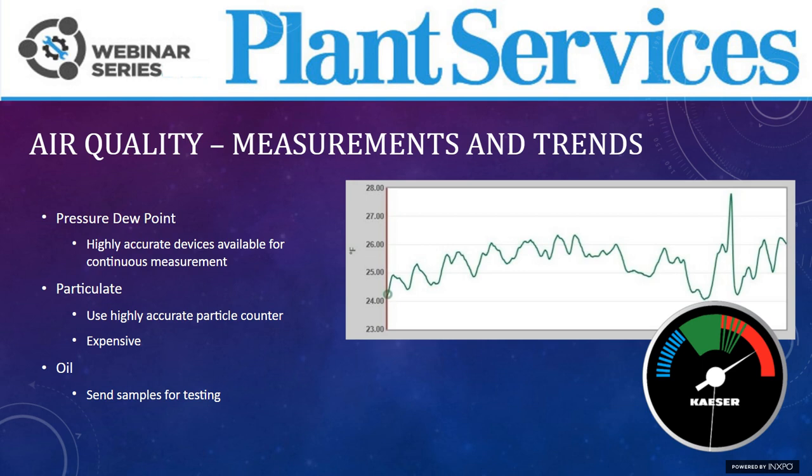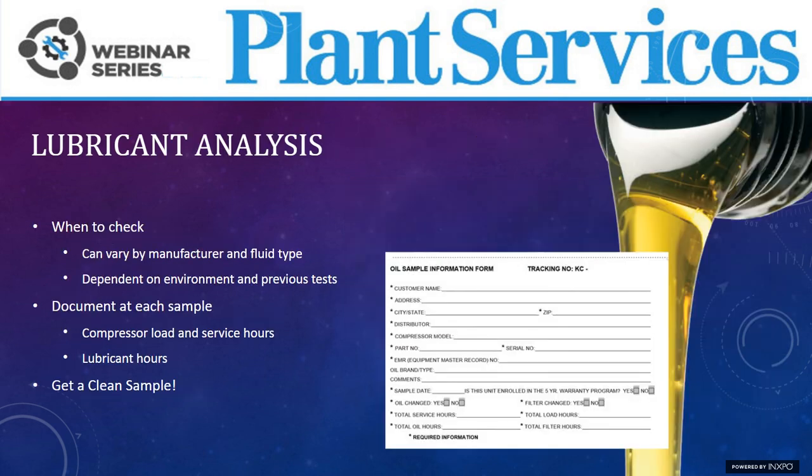So particulate and oil measurements, those are more difficult, but there are devices out there that can help you trend the data. But just be careful, as in order to get that kind of resolution, especially on particulates, you need high-quality devices, which are expensive to install. And for oil concentration, really, sampling can be done periodically and evaluated by a reputable third party to figure out your trends.